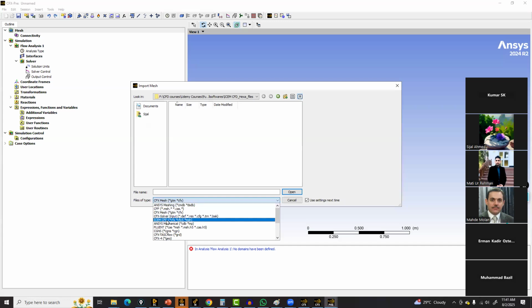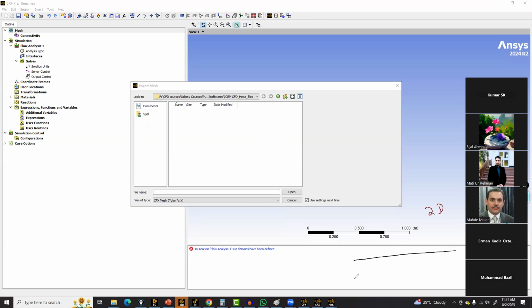Okay. One more thing that I want to point out here is that CFX doesn't have any 2D version. Okay, so no 2D version, it only works in 3D. So now the question is how we can work on 2D cases. Definitely we have 2D cases like we do in Fluent. So for a 2D case, if you provide the planar geometry, for example, the flat plate, then it will ask you to provide some thickness, and that will be used to actually make the 3D geometry.